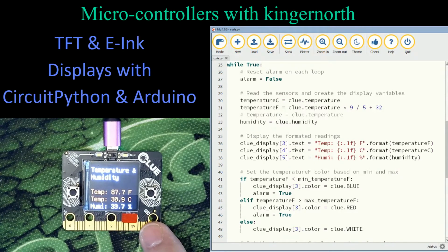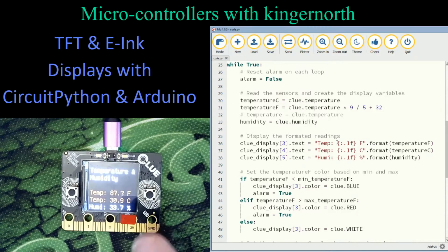So what we would normally do in Arduino, temp, colon, space would be on 1 line of serial print. The second line would be temperature F. And then the third line would be putting in the F, the space and the F, and then return so we can go to a new line. Here I can do it much simpler.